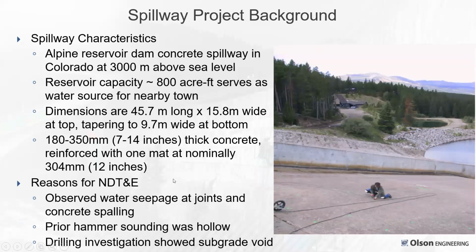The reasons for the project to be done with non-destructive testing and evaluation is the engineers had observed water seepage at the joints and concrete spalling. They'd done some hammer sounding and it was hollow sounding, which you can't always do through 7 inches of concrete, but it sounded hollow to them. In bridge decks, we think you can hear hollow sounds from corrosion and delamination down to about 3 inches, and then it's hard to hear deeper than that. And some limited drilling had shown that there was indeed a void below the spillway.